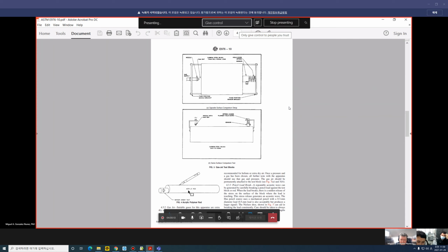And at each distance we perform 3 pencil breaks, one here, one here, one here. And we calculate the averages. And then we plot the results on an amplitude versus distance plot. And that could be a way to compare the sensitivity of the sensor.